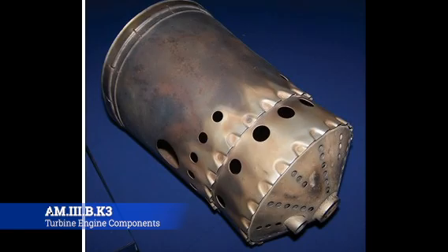Now the primary combustion air is directed inside of the can at the front end, where it mixes with the fuel and is burned. Secondary or cooling air passes between the outer casing and the liner, and it joins the combustion gases through larger holes towards the rear of the liner, cooling the combustion gases from about 3,500 degrees Fahrenheit to about 1,500 degrees Fahrenheit. Now, to aid in the atomization of the fuel, holes are provided around the fuel nozzle in the dome of the air inlet of the can-type combustion liner, which is why making sure that the injector or the spray nozzle is in the right place matters.